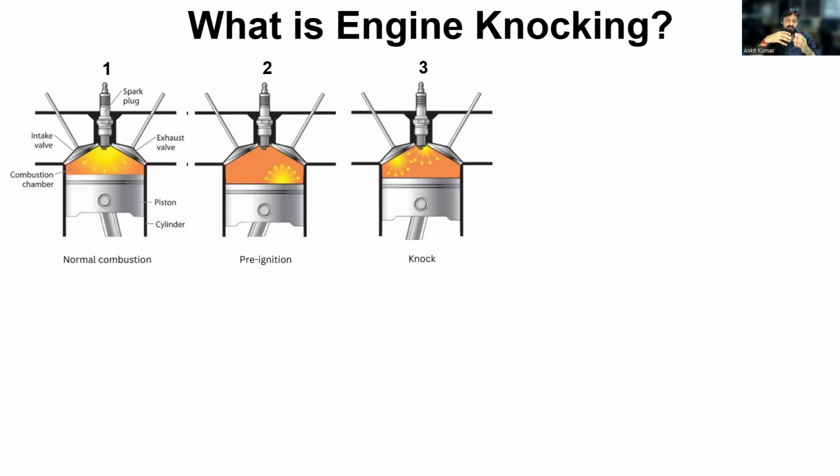Knocking occurs due to the pre-ignition of the fuel, and that happens for petrol because petrol contains various hydrocarbons, and all of these hydrocarbons are connected by weak van der Waals forces of attraction, or weak London dispersion forces. So if you compress this more, at higher compression the hydrocarbon molecules will get disintegrated into free radicals, and due to that compression these free radicals generate heat or get ignited, and that is called pre-ignition.